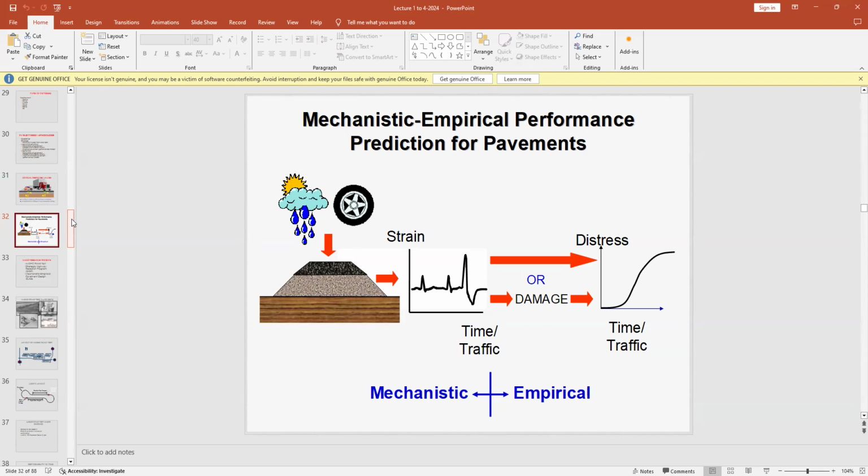If you design a thinner pavement, it will have more. But defining a thicker one will not be enough. You have to design a drainage layer or an asphaltic, granular base layer in such a manner that it can allow the water to pass through.